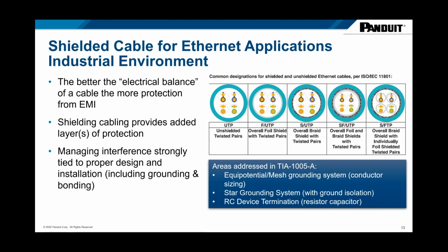In terms of the cable types, I mentioned cable balance. So a lot of times you're going to want to try to use unshielded twisted pairs, which is fine in a lot of spaces, right? And you can leverage that model to use UTP in that upper level of the installation very easily, right? But what we're telling you from a noise perspective is look at how well balanced and how well performing that cable is, even if it's not shielded, right? So have that well balanced cable and then figure out what types of noise you're dealing with and pick the appropriate cable.